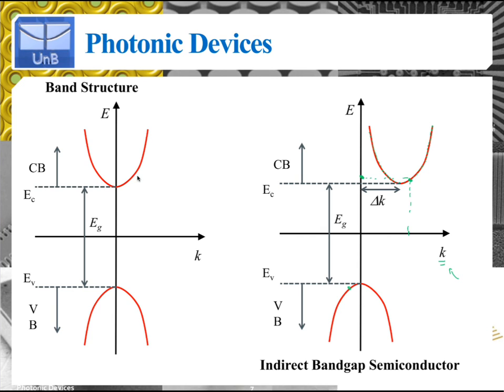Although the states are there, these are energies that can be acquired by the electrons. They will be empty. Once you give some energy in the form of temperature, electric field, or any other manner, some electrons can make the transition and occupy these states, leaving behind the empty states, which is what we call holes in the valence band.